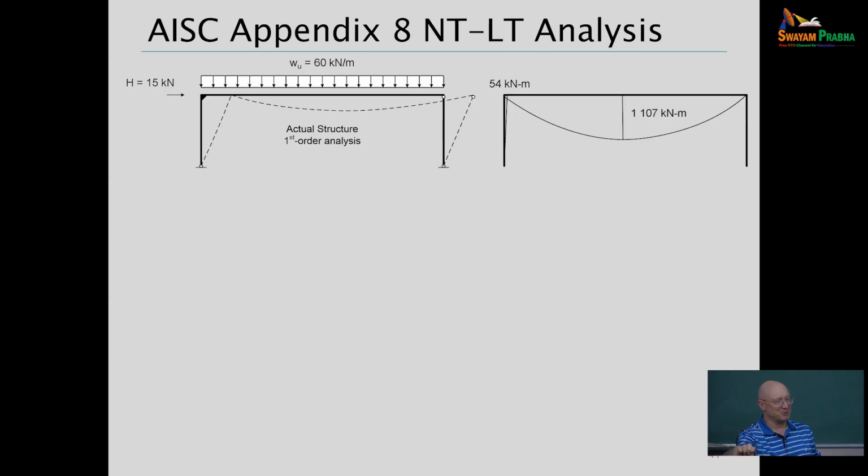So now you end up with a very interesting system where that short column, since it's short, sways and gets a very big P-large-delta effect because of its short length. So some very intriguing things are going on here with this frame. This is kind of the poster child of examples that can break some of the simple ways that we often like to use B1 and B2. So that's the nature of this frame.